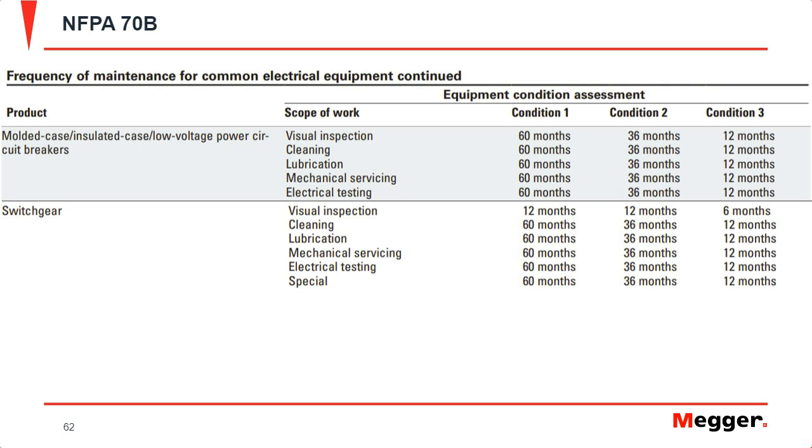There's not really a set interval for breaker testing. Common rule of thumb is, hey, every 3 to 5 years. Typically, you'll see breakers out in the field now with a sticker for NFPA rating and arc rating, making sure that they're tested every 5 years. Again, you can have ground fault testing every year, or you can just perform it every 2 years as a rule of thumb. But again, it's all going to depend on the company, the manufacturer's recommendations, and different aspects that can affect when you should test.